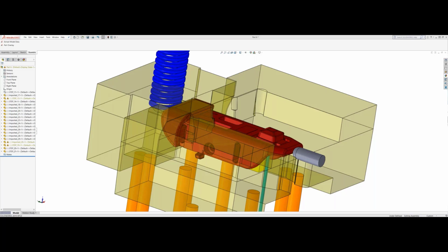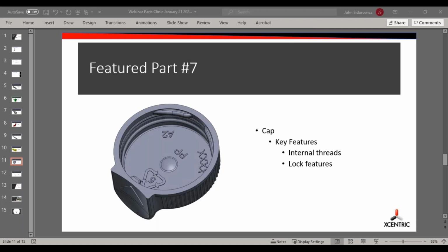Right, and we have a couple of customers that have multiple parts with us that all assemble together and form a unit, and obviously they want consistent color across all the parts. They can't have 3 different shades of gray or blue. As John said, if that's critical, it can be a battle using salt and pepper, and that's the point where we would suggest going to the pre-colored material to get that consistency that the customer wants. But again, as with anything else, it really comes down to expectations from the customer and what they're looking for.